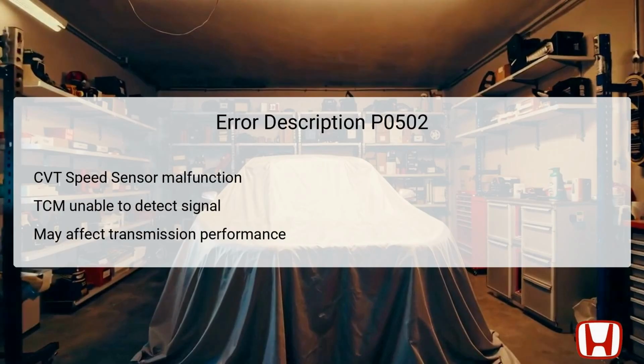If this communication is interrupted, the TCM registers an error, leading to stored DTC P0502. This situation can result in symptoms such as delayed shifting, erratic transmission behavior, or even the vehicle not shifting appropriately, ultimately affecting driving safety and efficiency.